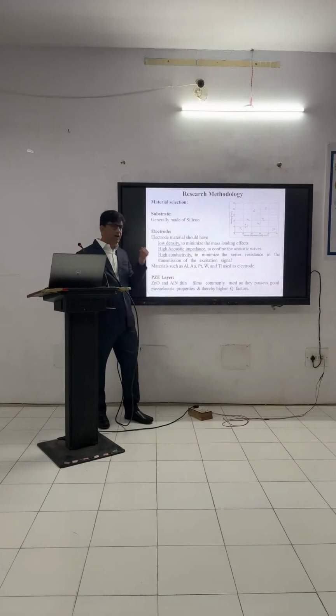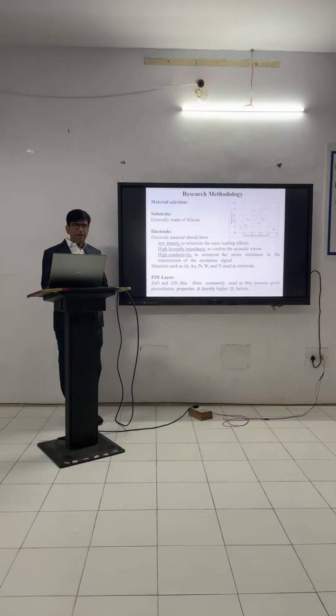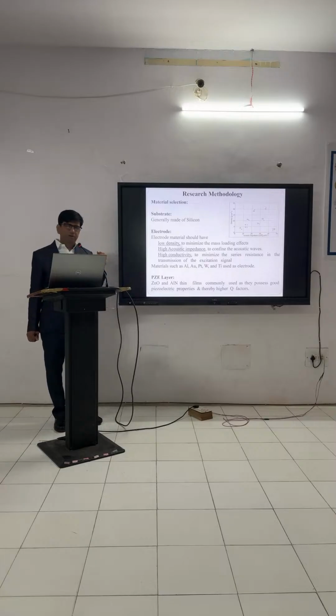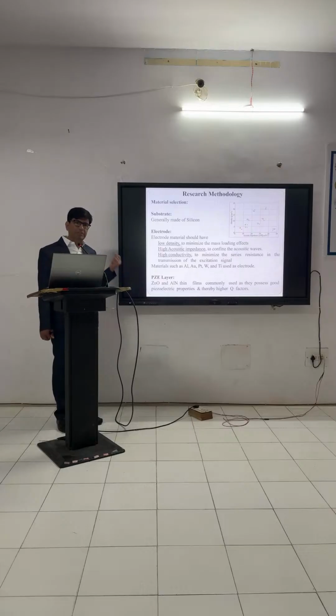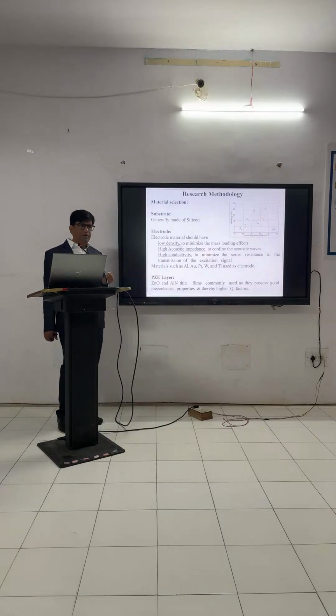Then we have the piezoelectric layer. Nowadays many piezoelectric materials are available: ZnO, aluminum nitride, and some ferroelectric materials available for the purpose of tuning your resonator. Today we will discuss ZnO, how to use ZnO to design your resonator.